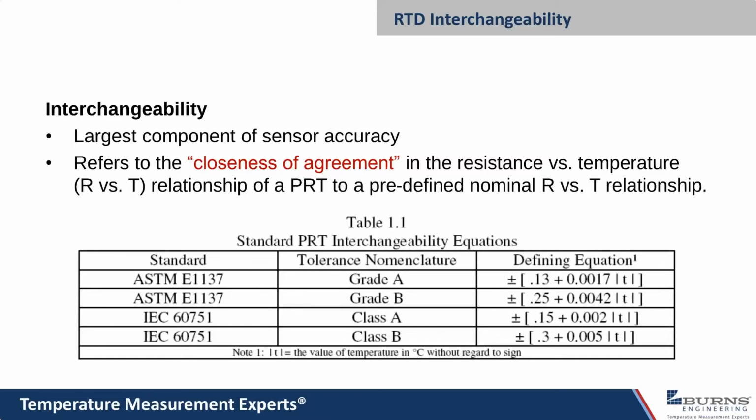There's also a thermocouple, which is a type, I don't know, sometimes I see it called a type C, and others it's a type W, but it uses one conductor that is tungsten. If you can imagine, it can do really high temperatures, but it has to be inside of a kind of an evacuated packaging system.